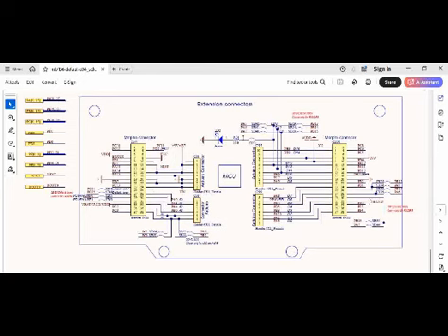So that means if this particular connector, for example the sixth pin, has to be connected to the PA5 pin, then this jumper has to be mounted. That means SB42 has to be mounted. And if this particular pin has to be connected to an LED on the board, SB21 has to be connected.